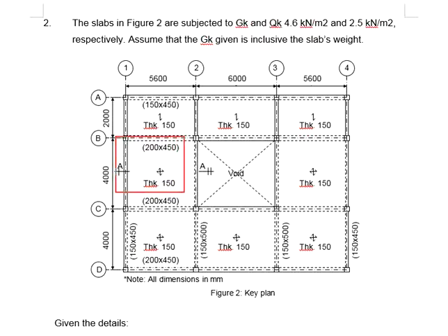For the slab that you need to design, at each corner you draw a 45-degree line, and then draw the lines so that they are connected well, and based on the divided areas, you may use those areas for you to estimate the loads taken by the adjacent beam.